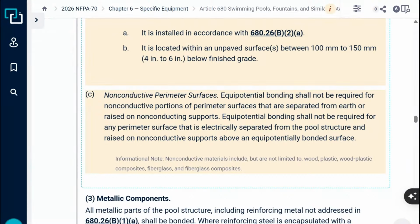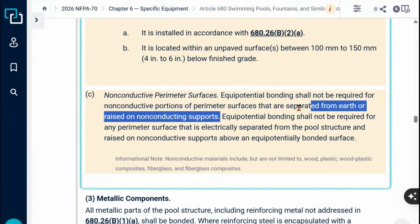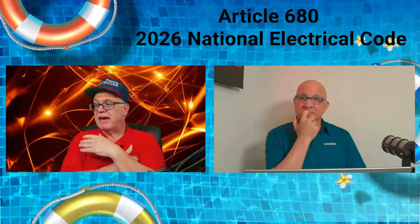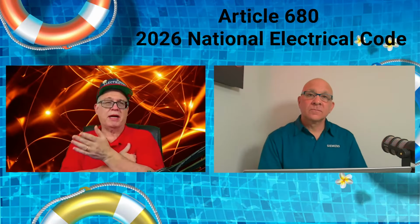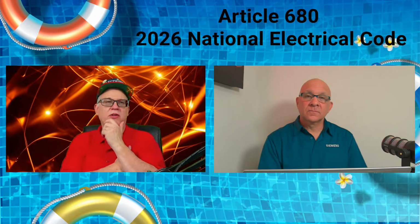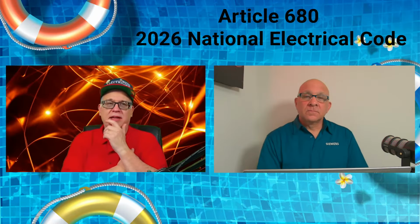So at some point something has to stop, right? The wood goes down to the earth, stops. The earth continues on. They are separate. So I think that's where we're at with that. Or they're raised on non-conducting supports, because at the end of the day, what I have to pull back to is that raised up, it's telling you I don't have to bond it. I don't have to have equipotential. If it's wood or non-conductive material sitting on it, it's also saying I don't have to bond it.